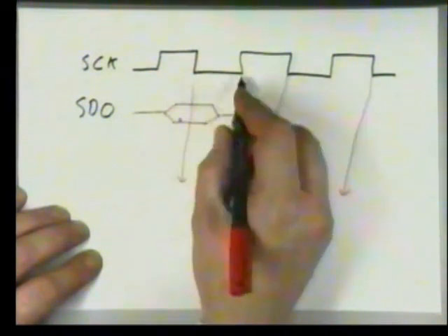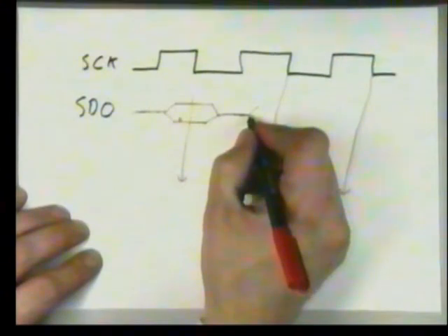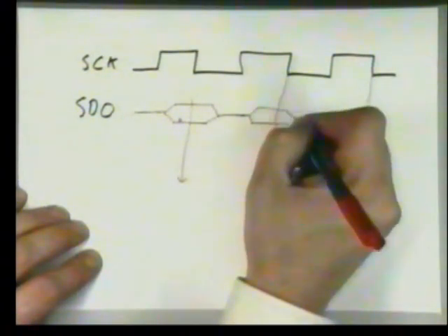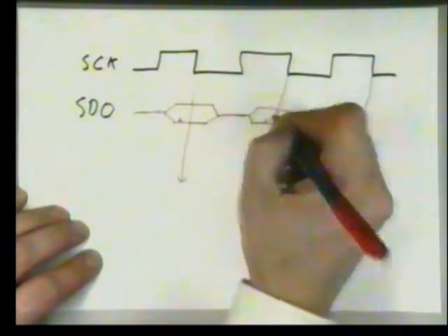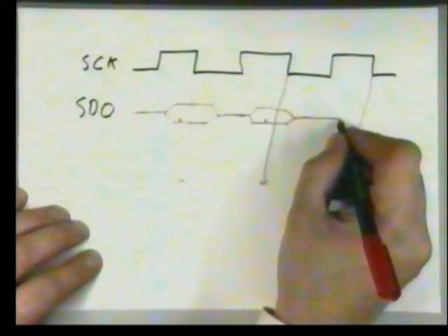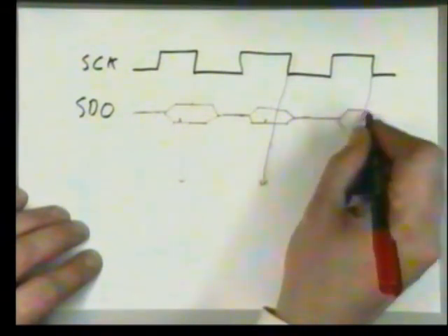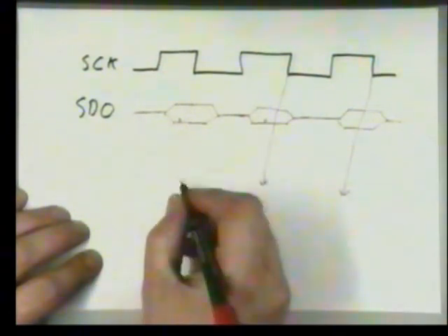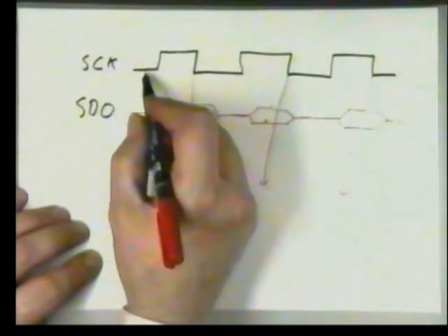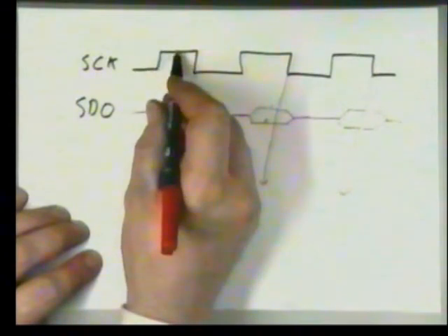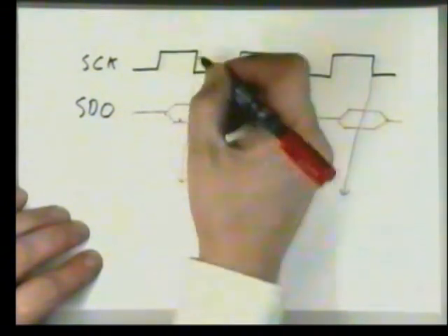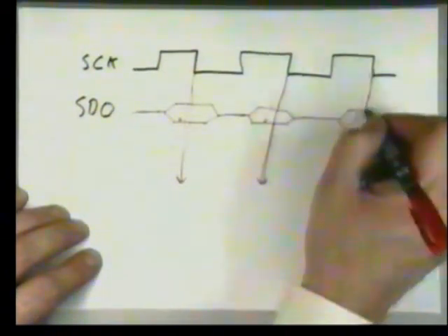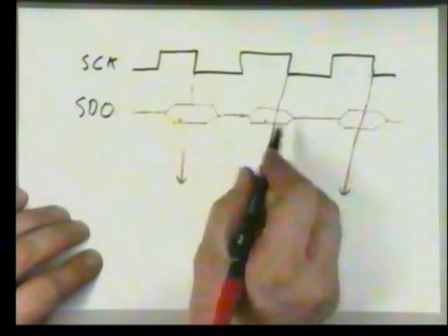While the clock has gone low and is changing state, we can output another bit. The rule is that on the falling edge it must have stabilized to a 1 or a 0. Now we can change it, output our new data signal, take the clock low. So here we have the ability to transmit 3 bits. As the clock is low and rising, we can change our state. On the falling edge, the data must be stable. So it's the falling edge that is used to clock the data.